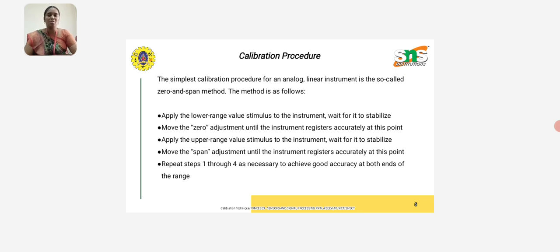Secondary calibration is further classified into two types: direct and indirect secondary calibration. Direct calibration is done by placing the standard meter in series with the device or meter to be calibrated and comparing their readings over the desired range. Indirect secondary calibration is based on the equivalence of two different devices using some similarity concept.